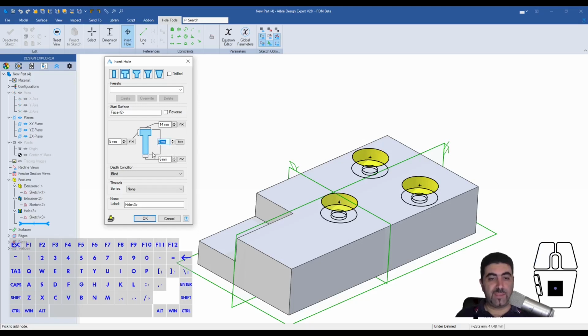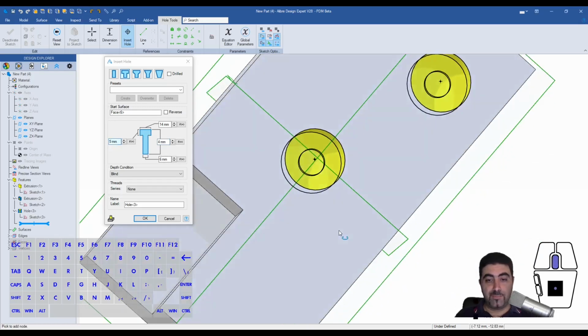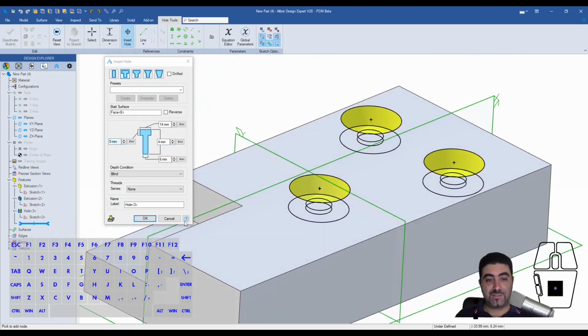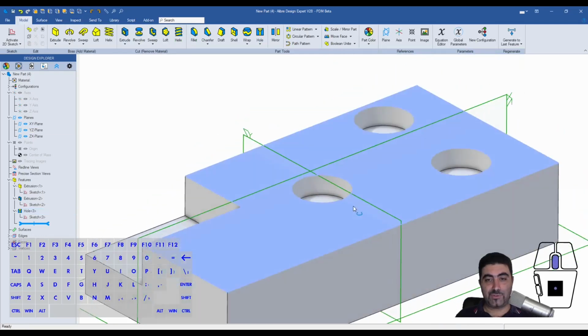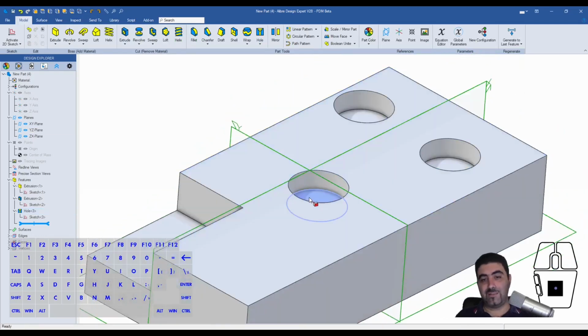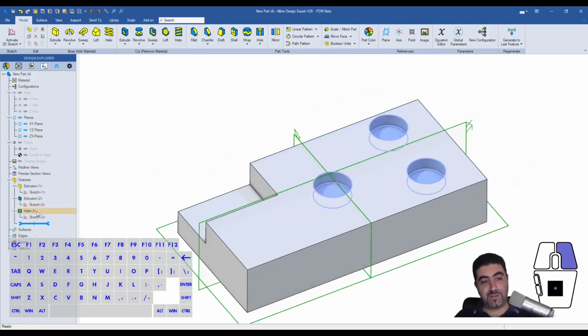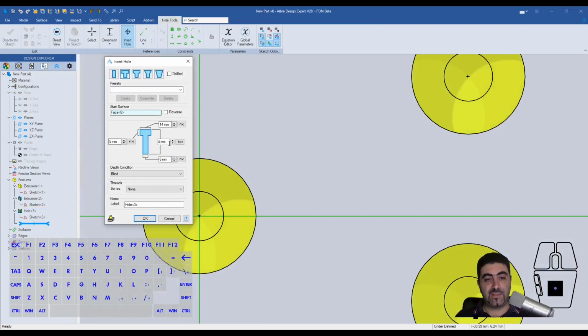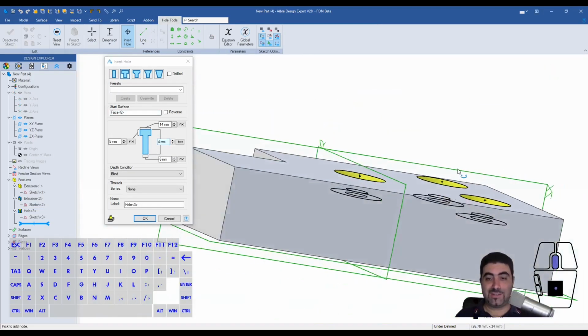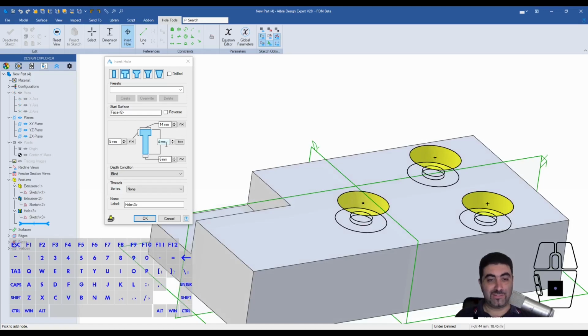By the way, if I give this a height of 4, this number, the total height of the hole, is smaller than the height of the counterbore. But you can see that Alibre doesn't really have a problem with it. You're just getting the counterbore, right? This might have a parametric use for you. It might not. You just need to be careful that if you set a total height that's less than the counterbore height, you won't get any of the smaller cylinder.